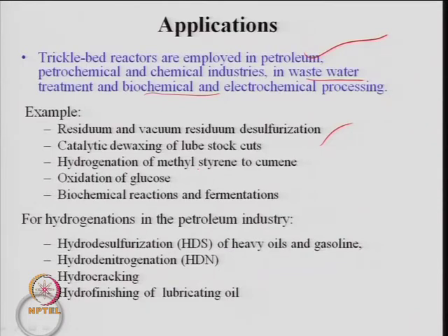For hydrocracking, cobalt molybdenum or nickel molybdenum type catalysts are used. So, trickle bed reactors are used for these processes, and hydrofinishing of lube fractions, which is again similar to what I discussed earlier in the case of catalytic dewaxing of lube stock. So, similar things are done by using the trickle bed reactor.